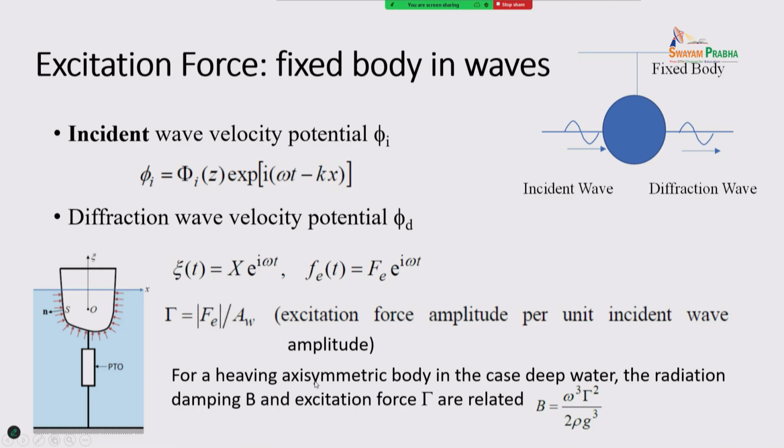In such a wave, if you have a symmetric, axisymmetric body in deep water, the excitation force and radiation damping are related.